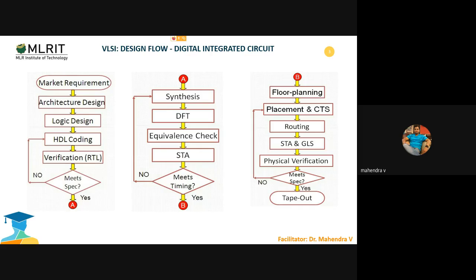Now I hope you understood the VLSI design flow we follow to manufacture integrated circuits or to implement the design on FPGA. Whatever this design flow shows is for semi-custom, not custom design. Here all this flow will work with the gate level netlist only. That's why we directly converted the HDL code into the gate level netlist. Now any query regarding this? If you have any query, I will take it up.